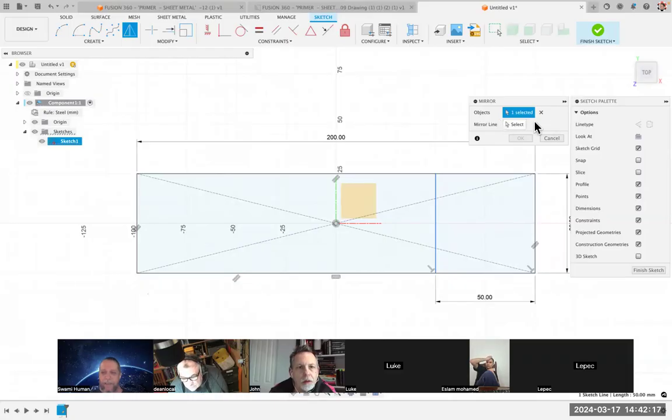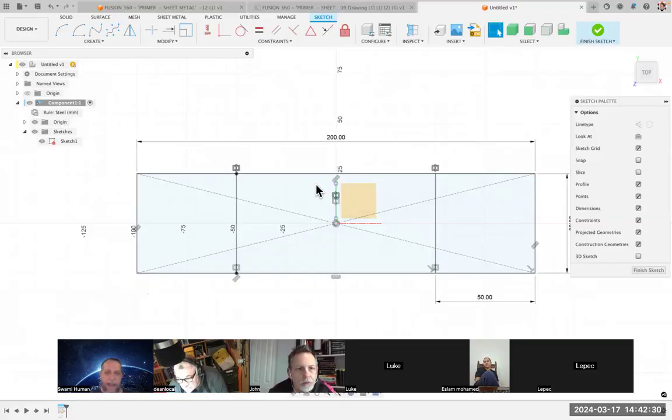So we need to come back to the dialog box here and get this select button for the mirror line. And that's why we made this one available to us, the green one. Click that and hit enter. And now we have a mirror symmetry icon here. If I click it, in the lower right there's a data info area people miss sometimes. That's telling me what I have selected. So that's all good. Go ahead and save, Control S, enter.